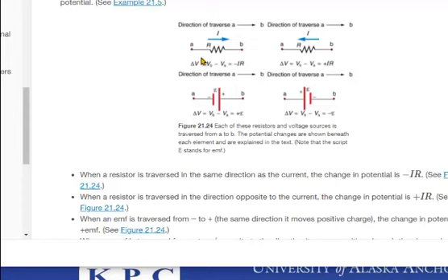As I said, when you have a voltage drop here, when you have a positive over here and a negative over here, which of course is indicated by the current flowing from positive to negative, notice because of the voltage drop, you need a negative in front of it. Sounds a little bit counterintuitive because you're pointing in the direction of the current, but that means the current is going from plus to minus, which means from a higher to a lower potential, hence a negative is necessary. And if it went the other way, then you would actually have a positive there.